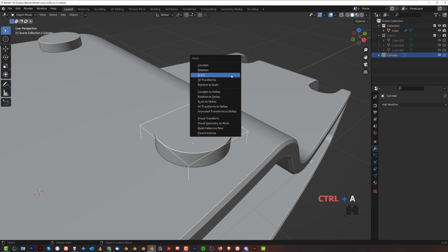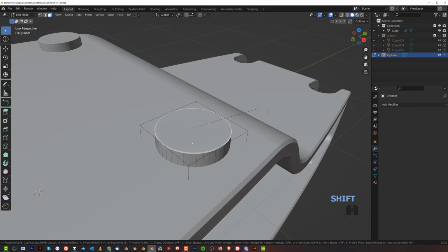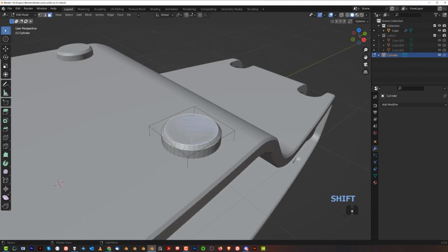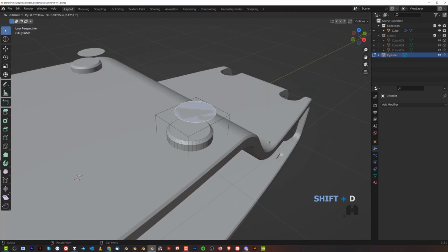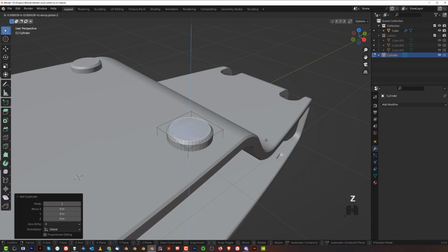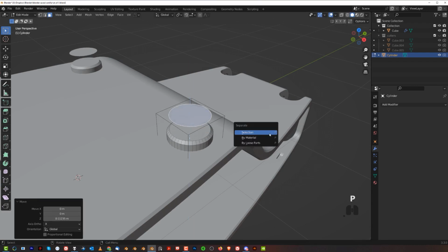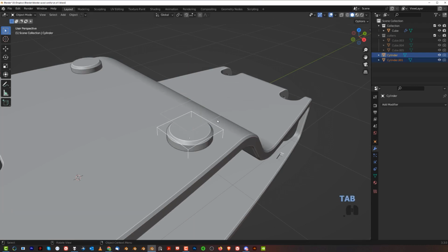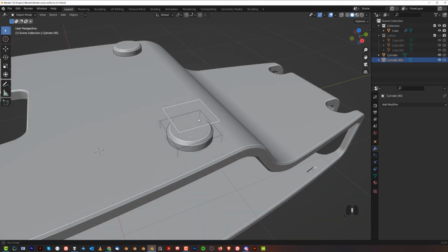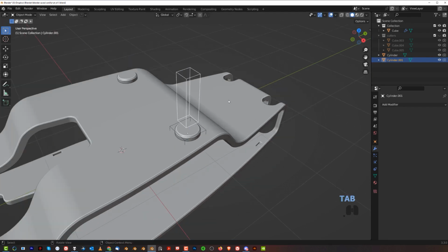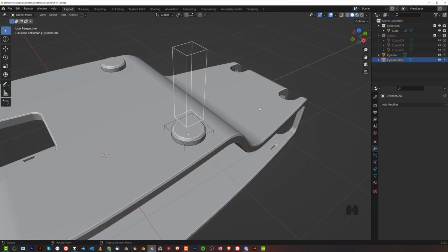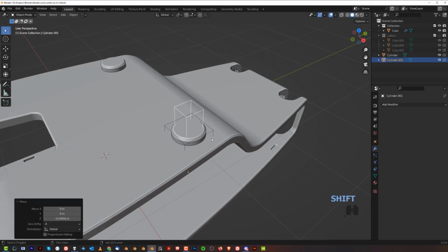And now with this cutter here, we can actually start editing it. So apply scale first, so Control A, apply scale, go to face mode, Control B, scroll down, create a chamfer, select the face, and in fact, let's just borrow this face. So Shift D and GZ here, P, and separate selection. Now we're gonna grab this face, okay, and we're going to scale this and extrude it up. And now let me see if it's gonna work. GZ and drop it down, select the cutter.